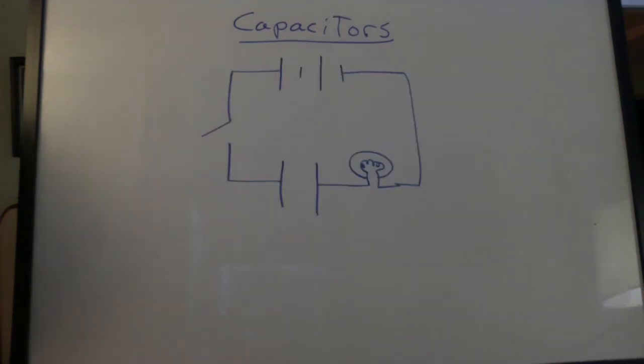This all agrees with the lab with the capacitor and the light bulb. When we closed the switch, the light bulb was bright because the current was highest. Eventually, the light bulb got dimmer, the current was less. And eventually, the bulb went out, and after a long while, the capacitor would be filled, and there would be no more current in the circuit.